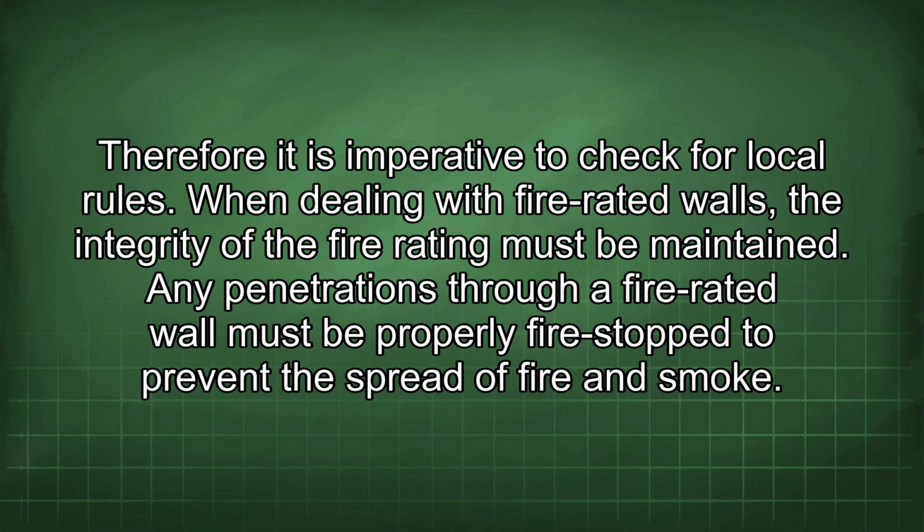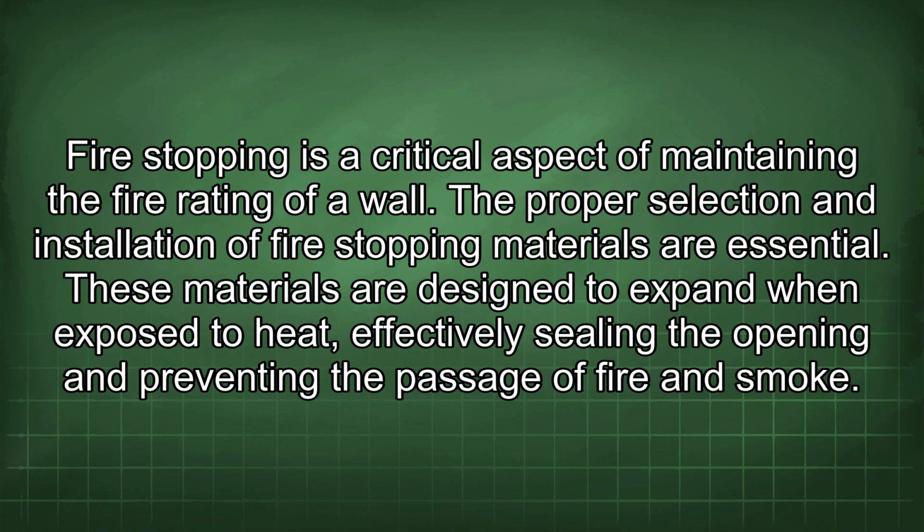When dealing with fire-rated walls, the integrity of the fire rating must be maintained. Any penetrations through a fire-rated wall must be properly fire-stopped to prevent the spread of fire and smoke. Fire stopping is a critical aspect of maintaining the fire rating of a wall. Proper selection and installation of fire-stopping materials are essential.